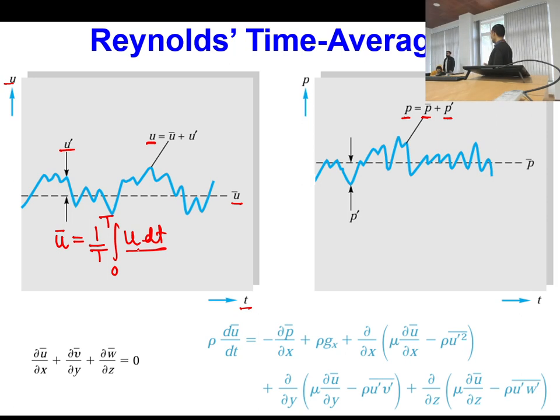That is the simple meaning of u bar. What I have done is consider some time scale, and in this time scale region, whatever the variation of velocity is, I am integrating that with time and then dividing by time. So that will come out as nothing but my mean flow velocity. Mathematically, whatever this dashed black colored line is, it is computed from this relation.